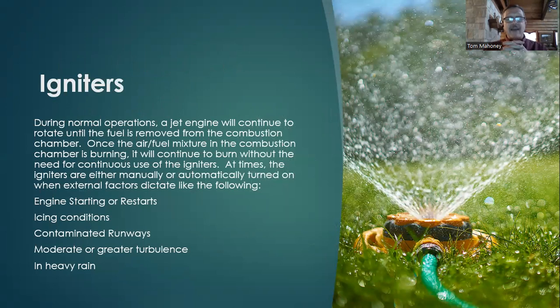Let's talk about the igniters, which are actually like little spark plugs that lit the fuel off to begin with when we were starting the engines. Of course, we don't need the igniters on all the time once the engines are running. However, there are times we would like to have the igniters running just to make sure that the flame continues to burn inside the combustion chamber or the burner can.